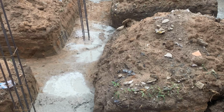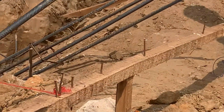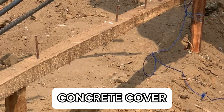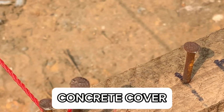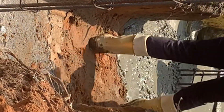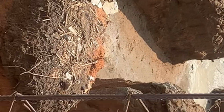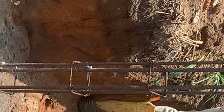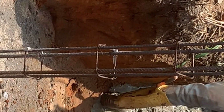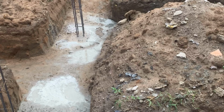Now, what I want you to take note of is that care must be taken to ensure that there is adequate provision for cover before placement of the mixed concrete to the position. Please don't forget. And again, during placement, ensure not to pour the mixed concrete from a high distance to avoid separation of the materials, and this can lead to poor concrete strength. Please take note of that.